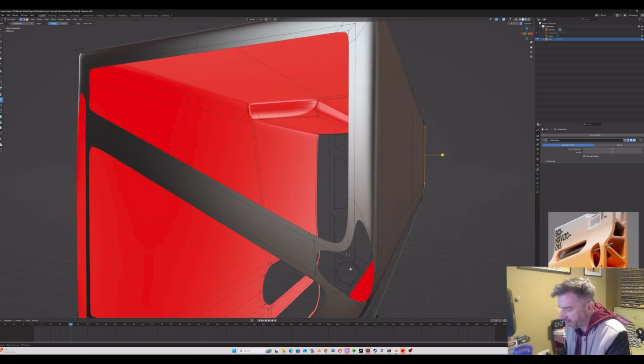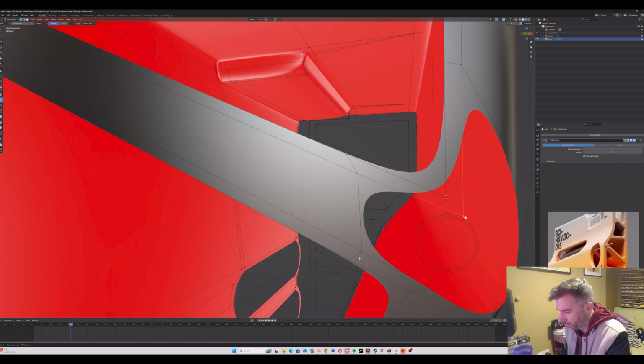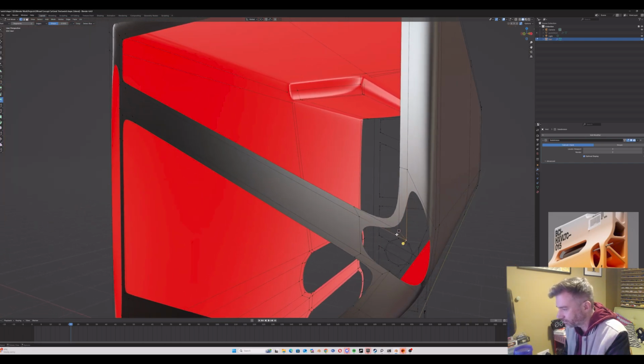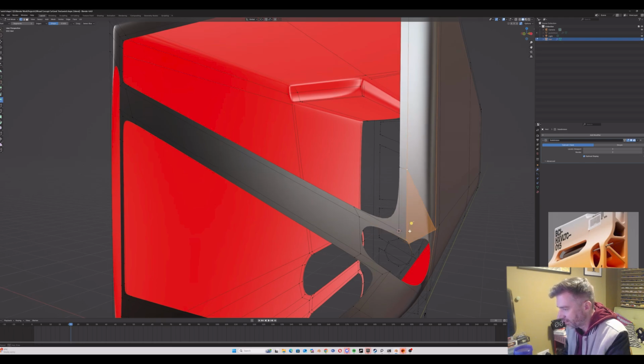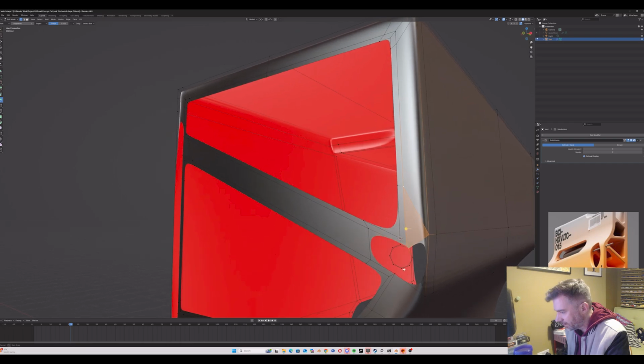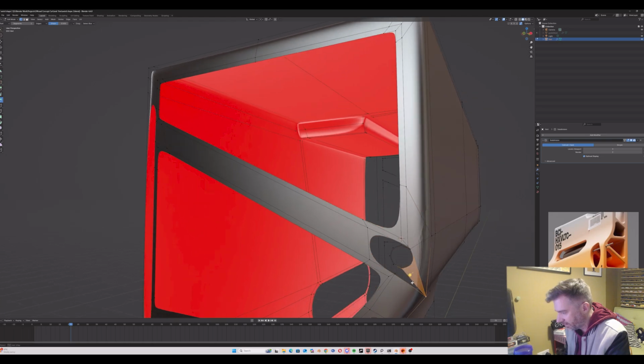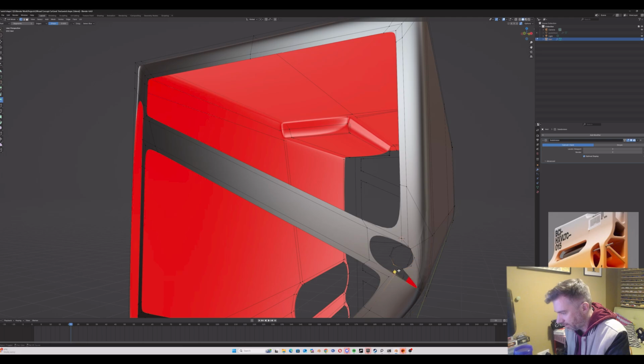So we just want to connect all of these to any point that we can without ruining our geometry. So we're looking for quads wherever we can find them. So there's 4 points here. So that's the start. And we could actually connect these 4 together like this. And then these 4 can also connect to that. And then maybe we do these 4 to this. These 4 here. So we're always building quads.